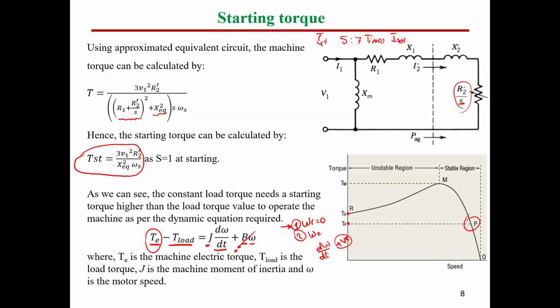Okay, and for any motor, guys, the torque will start from 0. So here we have Ts equals value, but this is actually not the instantaneous torque. This is the average torque. But the real characteristic of the motor, I mean the torque with time, is going to start from zero. At zero time, or at the starting point, it will start from zero value and absorb current and increase.